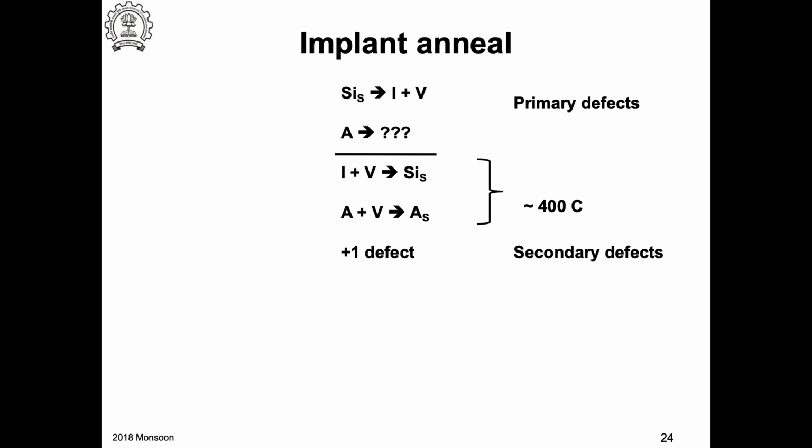We have discussed previously that a lot of processes, for example oxidation and diffusion, are controlled or influenced by the presence of defects in the silicon. So when you do the ion implantation and you try to anneal the damage, you will always create defects. Anything that you do after this, you have to take this into account. Very important.